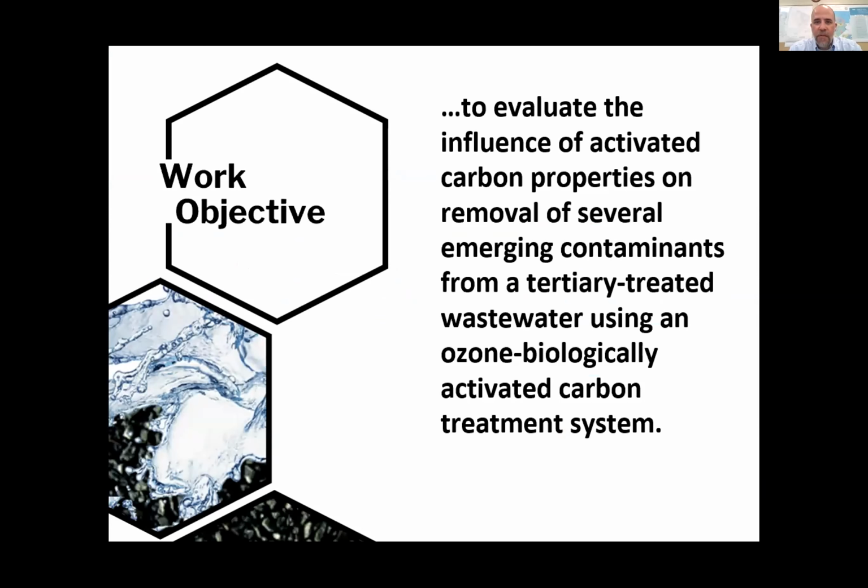So we had a tertiary treated wastewater that we installed an ozone BAC pilot unit downstream of that water to then look at several activated carbons, not just from the perspective of grain size and other properties like effective size or uniformity coefficient, those things that would influence particulate removal, but to look at how the surface chemistry of that carbon might impact things like the contaminant removal. And then also one of the outcomes was just how serviceable that carbon is. In other words, the backwashing frequency of that carbon was something we discovered that we're investigating further. That was a bit of a surprise.